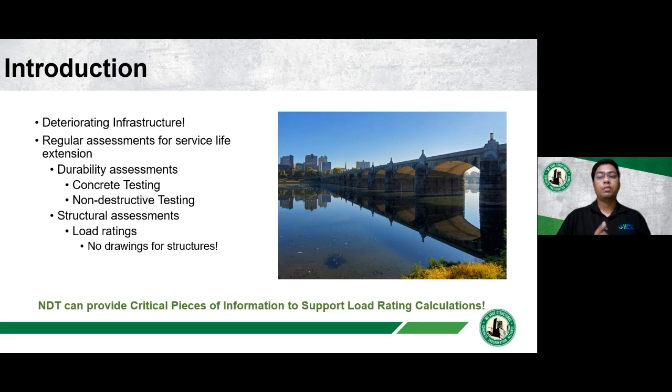However, more often than not, we do not have access to the original as-built drawings, or they are not even available for load rating calculations to be undertaken. And this is where non-destructive testing methods could be used to fill the information gap and reliably load rate the bridge.